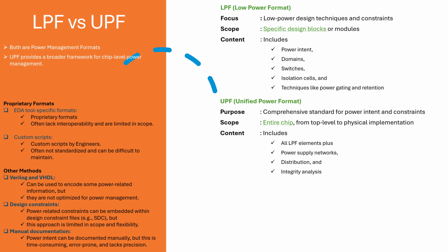analysis, etc. But to summarize, both LPF and UPF are power management formats to capture the power intent, to enable the proper power management during the design cycle. UPF provides a broader framework for chip level power management, whereas LPF is a subset of UPF.